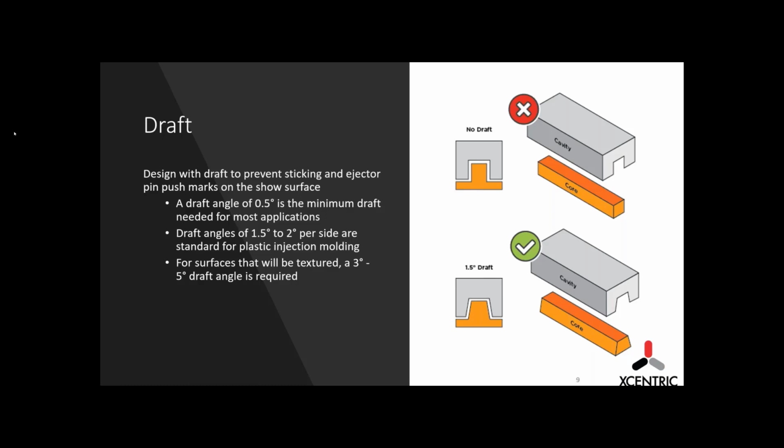Follow up to the question about the runner diameter. Why ask runner diameter? Because if your part is big and your runner diameter is small, then your runner can cause the cavity not to fill. I can't quite tell what they're asking here. Seems like your runner can cause the cavity not to fill. I'm not sure.